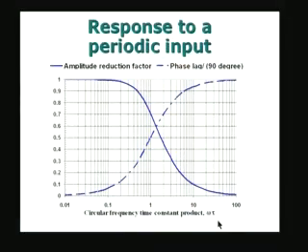The important parameter which is going to play a role in this particular case is the product of omega, the circular frequency, and the time constant tau, the omega tau product. Of course, the omega tau product can go from anywhere from 0 to infinity in principle, that means very small values to very large values. If omega tau tends to 0, obviously it is like steady state, there is no variation with respect to time, and when omega tau tends to infinity, that means that the input frequency is very high or the time constant is very large, one or the other.